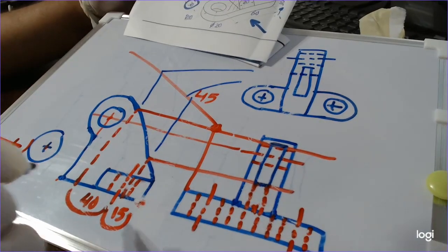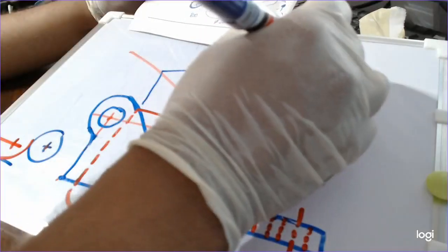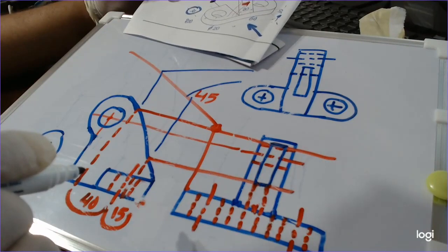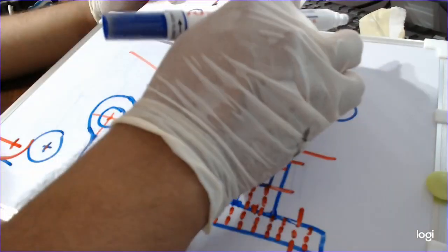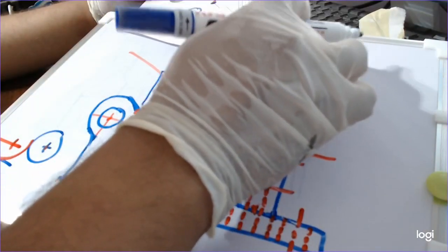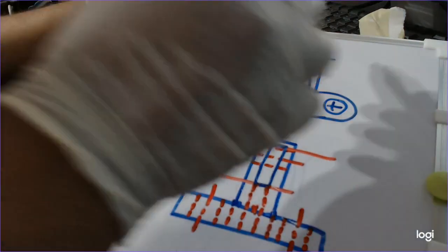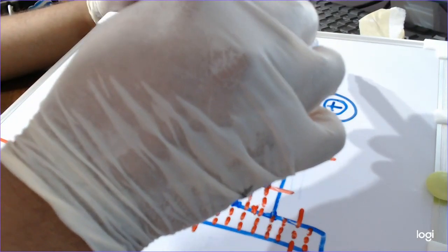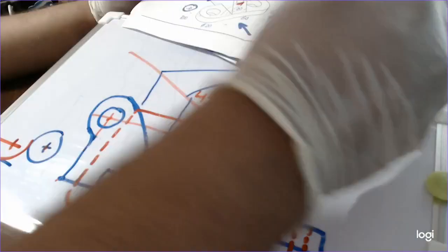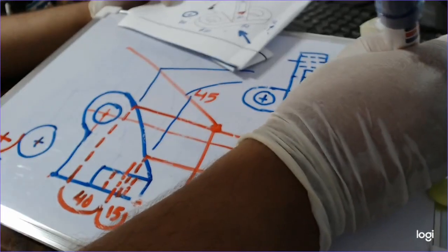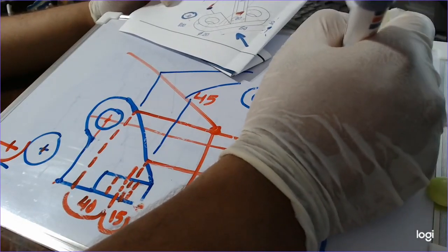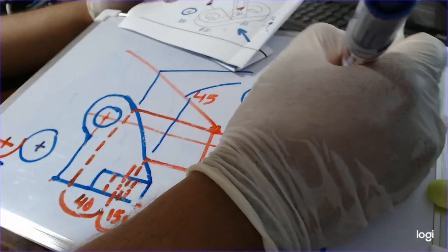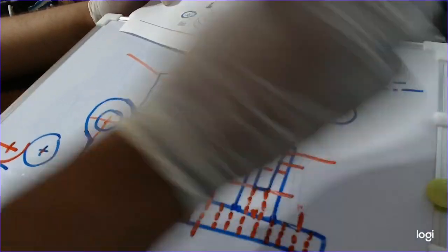Okay, so after taking the projection, actually it will be on the center line, I'm sorry. So if we have this edge with the center line, the center line will be dominant. Okay, so if we have a dash line and we have a center line aligned on this dash line, the dominant one will be the center line. So you have to draw the center line.